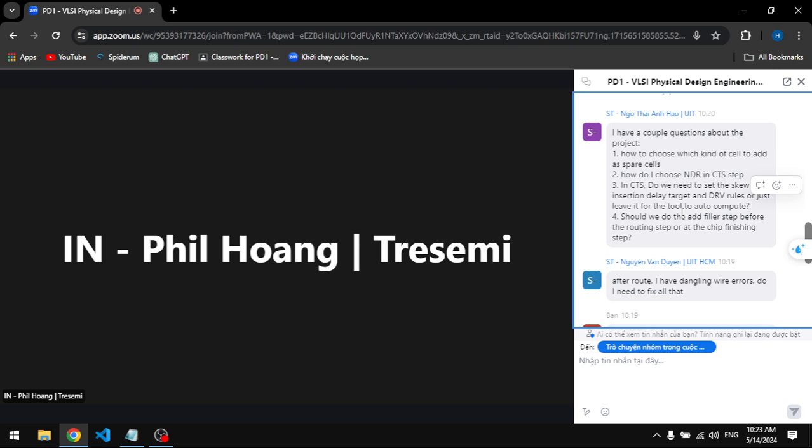If you have sharp rise and fall time requirements, meeting them would require inserting too many buffers because of your narrow width. So you want to give it double width. But the expense of that will be power, because your double width wires will have high capacitance.